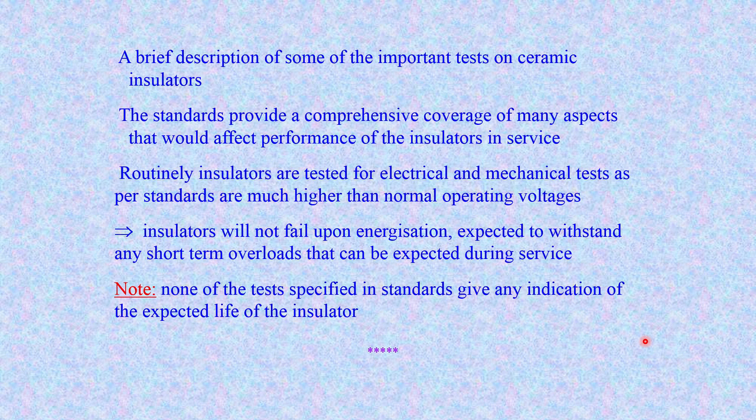We know that standards provide a comprehensive coverage of many aspects which would affect the performance of the insulator strings in service, a very important point. Routinely these insulators, ceramic or glass, are tested for both electrical and mechanical tests as per the international specified standards, usually at slightly higher than the normal operating voltages.